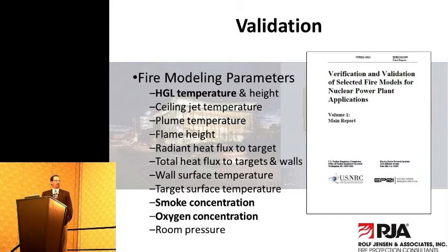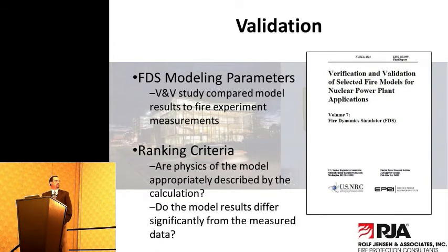And of course, all the tenability criteria that we chose to compare to need to be run by the stakeholders in advance, so everybody's on the same page in regards to this particular project. So these are all chosen in advance, but we did not choose to go into looking at ceiling jet temperatures specifically, or the impact of a fire having a secondary item ignition. So flame spread wasn't an issue, or radiant heat flux to targets was not an application that we needed to worry about in regards to verifying and validating.